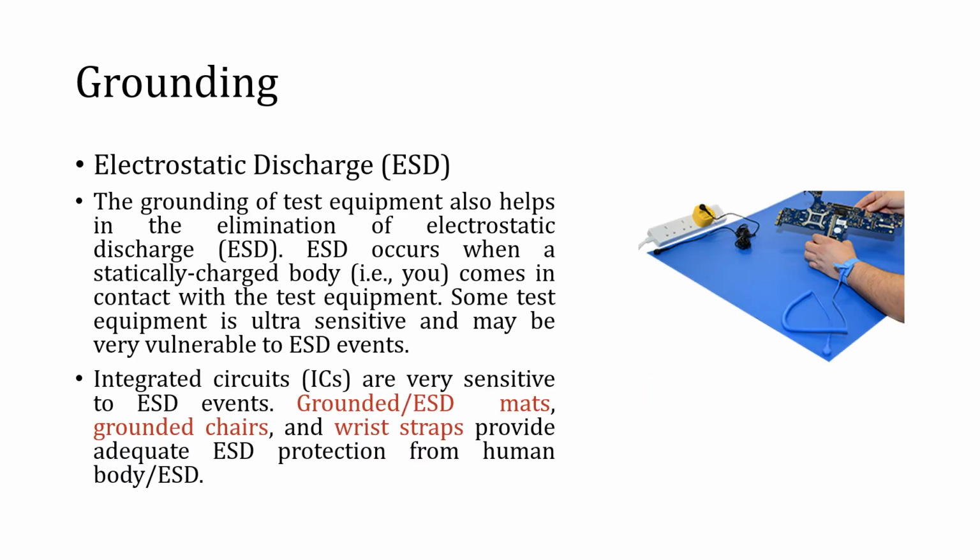Okay, coming to the next thing is electrostatic discharge. This is very important when we are handling some very sensitive circuits, especially memories or CMOS based circuits. They are very sensitive to electrostatic discharge. Since we are now using polyester kind of clothes and plastic chairs, when we keep on sitting, or due to rubbing of our clothes with the other sitting material, there is always a possibility that we are carrying a static charge.